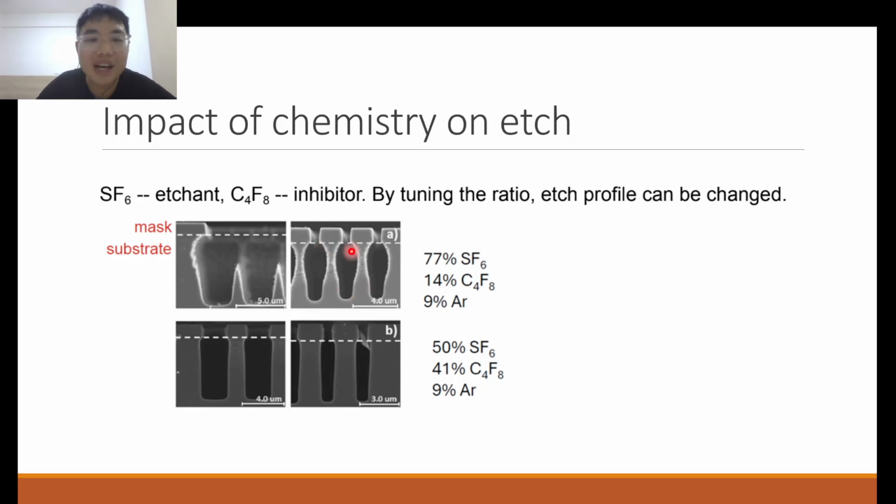And here's a good image, for example. Let's say maybe you are an engineer, and you see this diagram. Wow, this is not good, because in your etching profile there's what we call a bowing effect. So it's basically not a good clean anisotropic etch. There's poor protection of the sidewall.